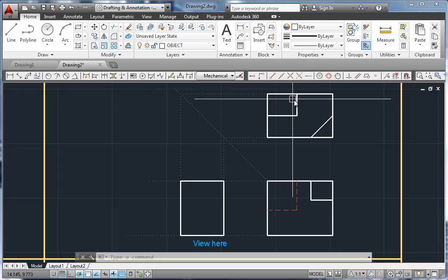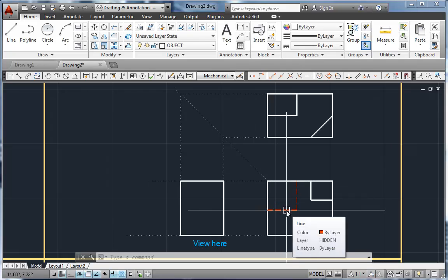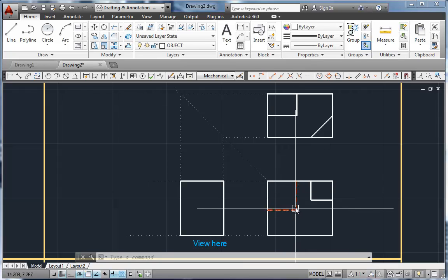So this rectangle has to be a surface because it's got edges. When I look in the front view, I can see that that surface is exactly the size of this line. So I'm going to assume that this hidden line is a flat surface that's down in this far, and it is a straight cut down. So there's a big notch out of the back left corner of the part.